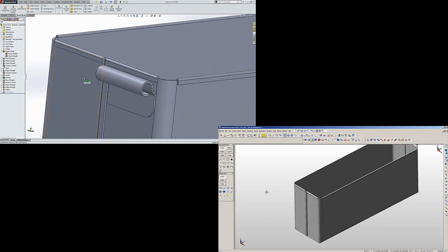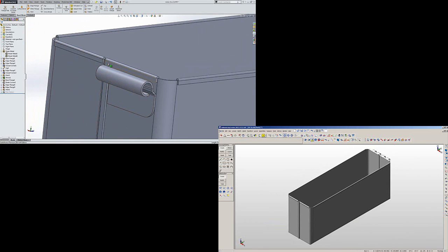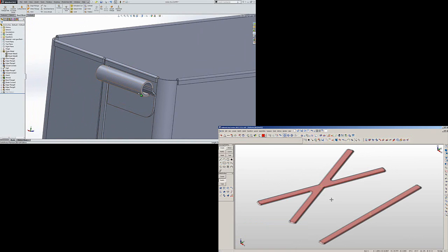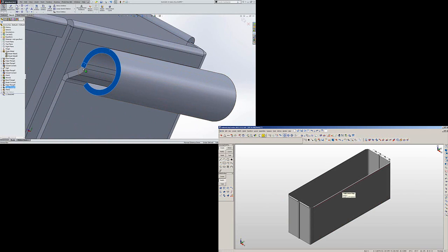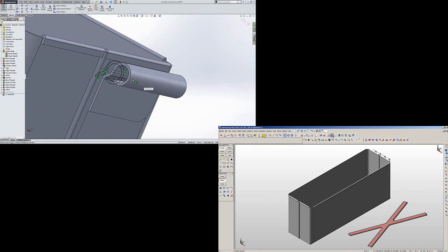Okay there. Alright, so the next thing we want to do is actually cut this up so we get each individual hinge. So I'm going to open a new sketch on the right plane, and I'm going to select this face and this, and this, and that, and I'm going to convert those entities on the sketch plane. So I can use that sketch now to actually cut away my hinge.